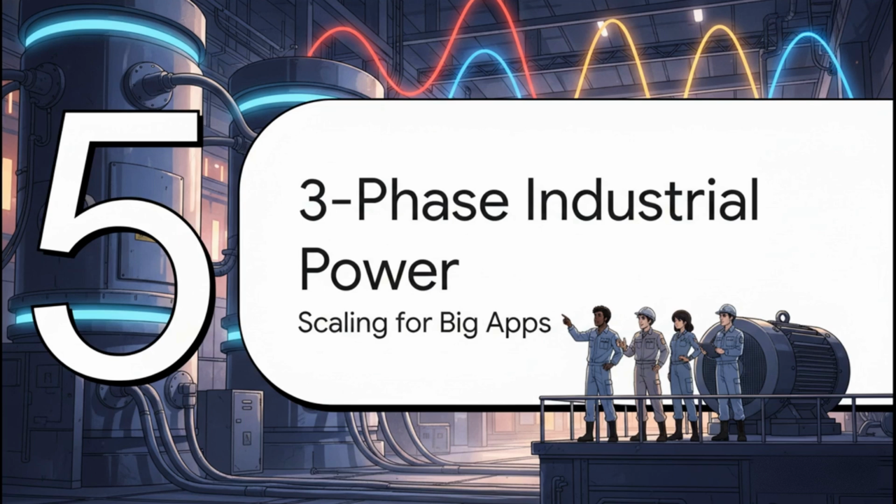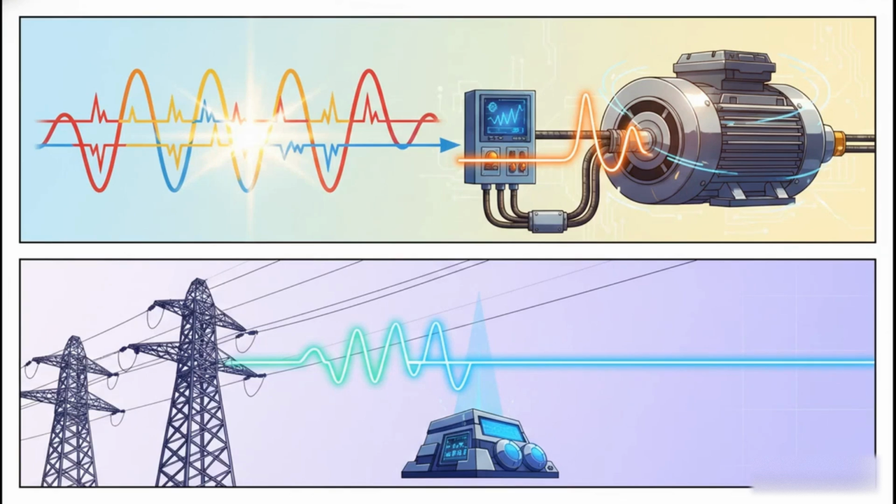So far, we've been talking about single-phase power, the kind you find in your house. But when you get to serious industrial applications, we've got to scale everything up to three-phase systems. And this is where AC voltage controllers become absolute workhorses, controlling massive motors and even helping to stabilize the entire power grid. You know, three-phase systems have a really cool built-in advantage. In a balanced system, some of the most troublesome harmonics, called triplens, like the third and ninth, just naturally cancel each other out, so your power quality is better right from the get-go.